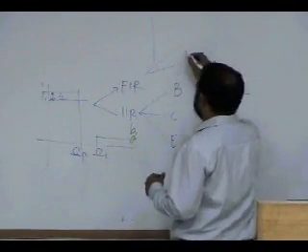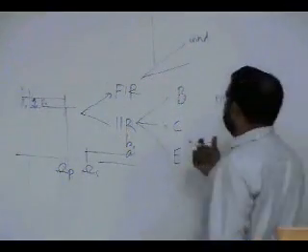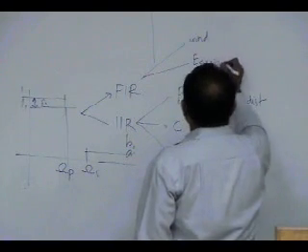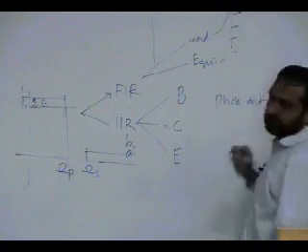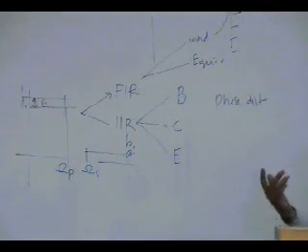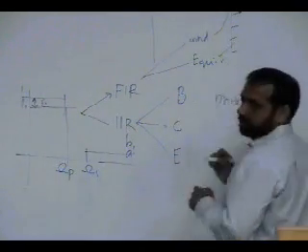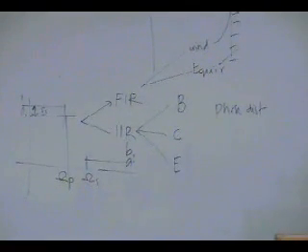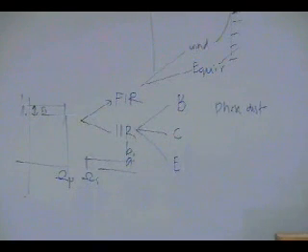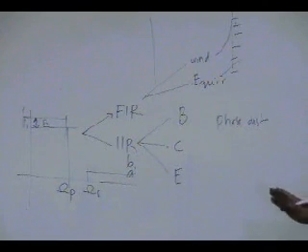An FIR, you know, the windowing method is one, and minimizing the maximum error is the other one, which gives you an equiripple filter. And in the windowing method, there are so many windows. Perhaps the best is to use a Kaiser, and Kaiser will give you the order of the filter as well. But the optimal one is equiripple. That you say, let's do the equiripple design. Equiripple design will give you the most economical filter. Similarly, FIR can also be designed adaptively.